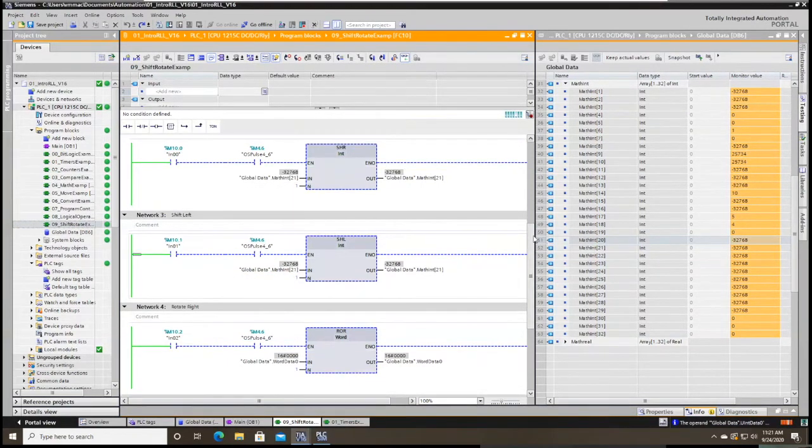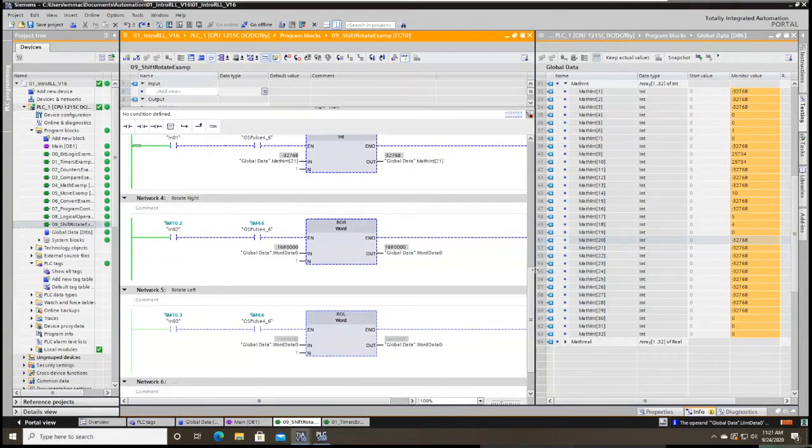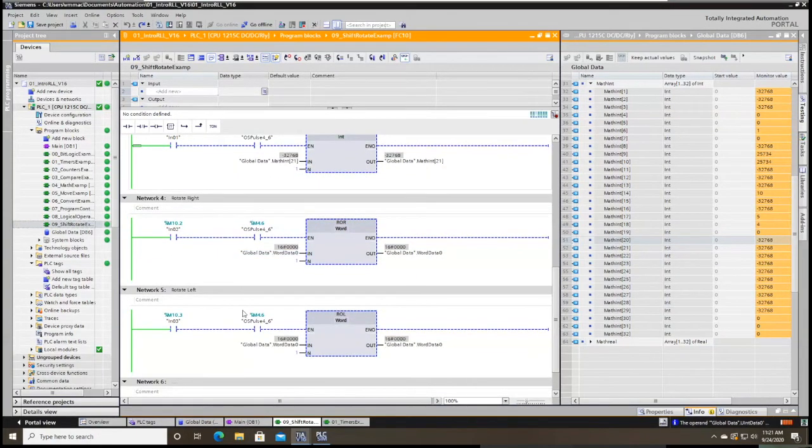This just gives you some different ways that you can manipulate bits within a tag. Same with rotate right and rotate left. Rotate right kind of does the same thing as the swap function in the sense that it rotates all the values in a bit. Say for example, we had a byte, 8 bits, it would rotate all those values to the right and kind of flip them. And same with the rotate to the left, it does the same thing. It swaps bit by bit. For rotate right, it would do everything to the right. Rotate left, it would move everything to the left.